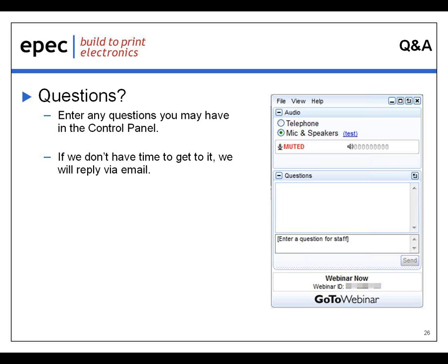Conventional flexible membrane keypads use polyester substrates or sheets, typically 5 mils thick, with screened silver-filled polymer conductors. The polyester material is picked because of the material's memory, and with repeated pressing it doesn't cause permanent deformation of polyester. In other words, the switch will return to open when the user's finger is removed.